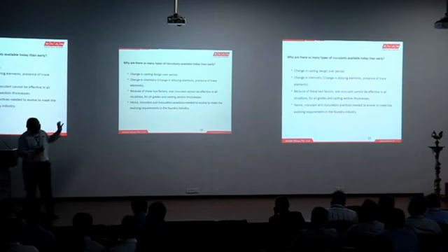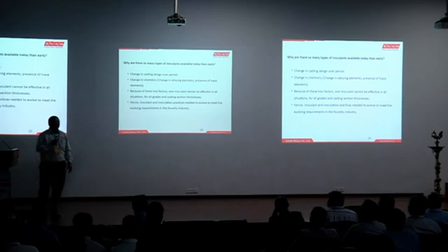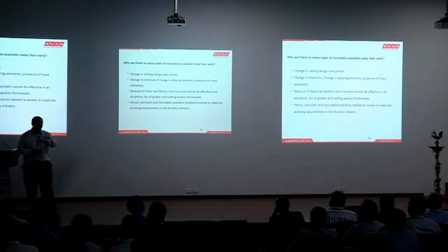There was a huge requirement of uniformity in the casting. Say for example, today people are talking of getting the same nodule count from a very thin section casting to a very thick section casting. So I should have one inoculant which can serve shrinkage control in one section, and the same inoculant should serve carbide control in another section. When these kinds of multiple requirements come up, multiple elements are required to be added